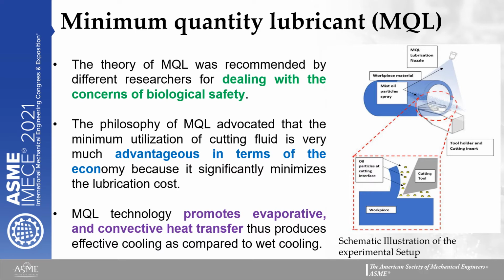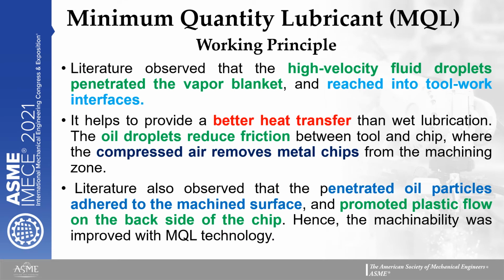MQL technology promotes evaporative and convective heat transfers, and it provides an effective way to cool down the cutting tool as compared to wet cooling. The effectiveness of MQL technology is linked with the high velocity fluid droplets that penetrate the vapor blanket and reach the tool-work interfaces.